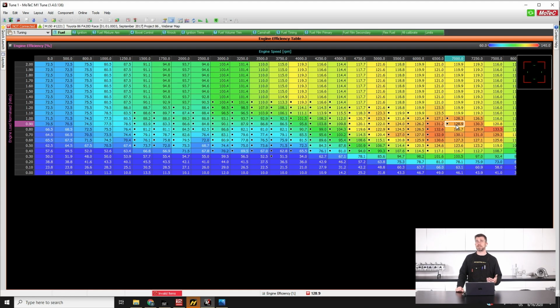However, we also do need to account for, and it's a little bit outside of the scope of this webinar, but I just want to mention it, the fact that you will find, particularly if you're competing at the likes of Pikes Peak, if you've got a turbo setup that's optimized for sea level operation, you're almost certainly going to find that you will end up overspeeding the turbocharger if you want to try and maintain a fixed manifold pressure in the inlet manifold as the car climbs up the hill. And this relationship here between inlet manifold pressure and exhaust manifold pressure also answers one of the other questions I often get asked.